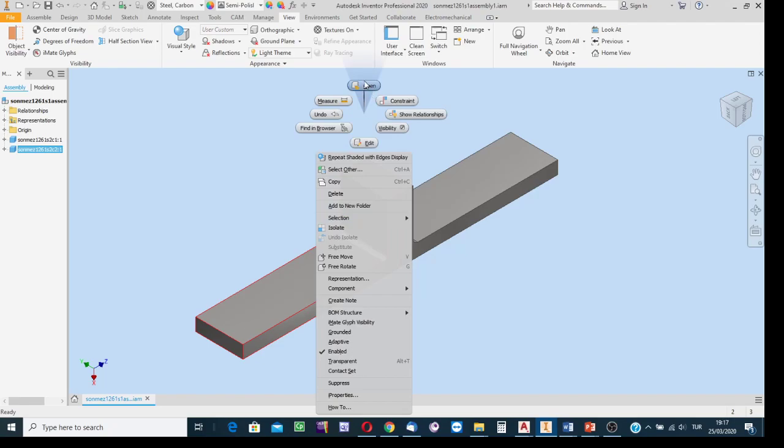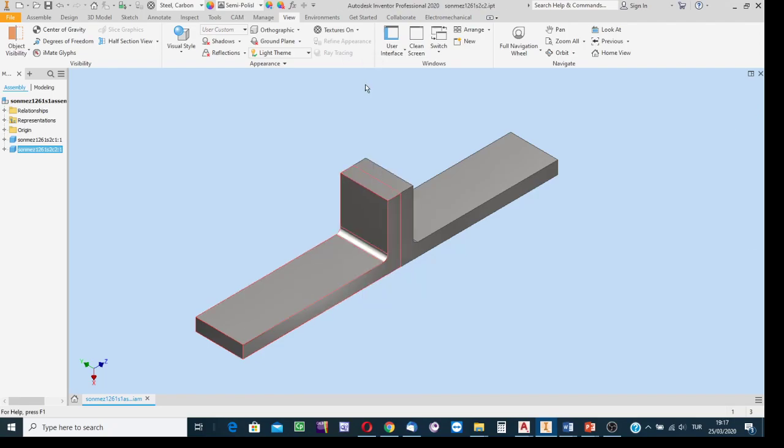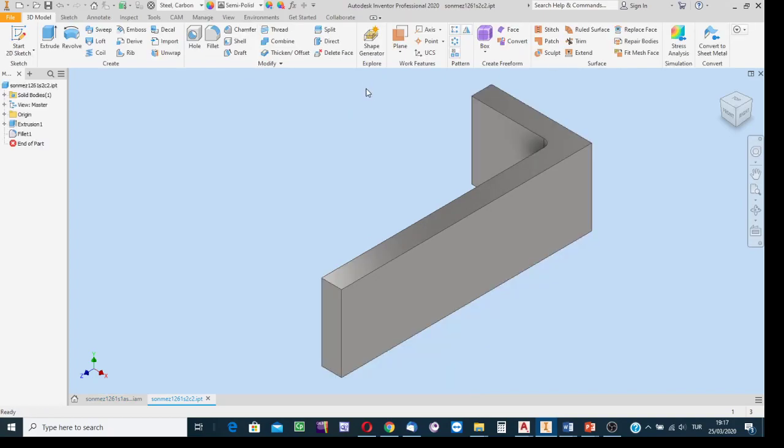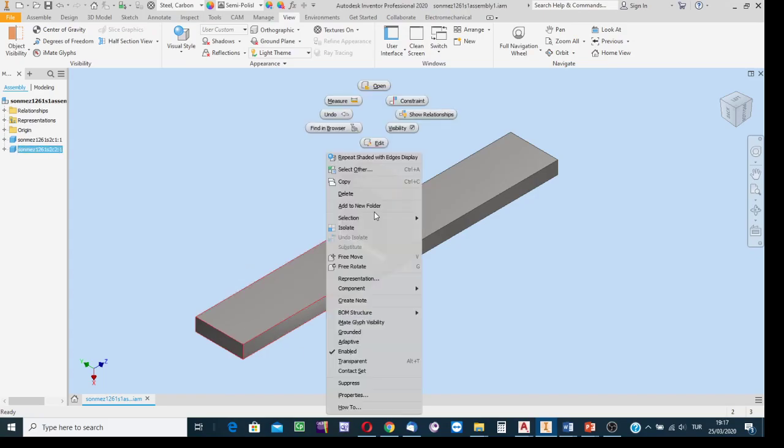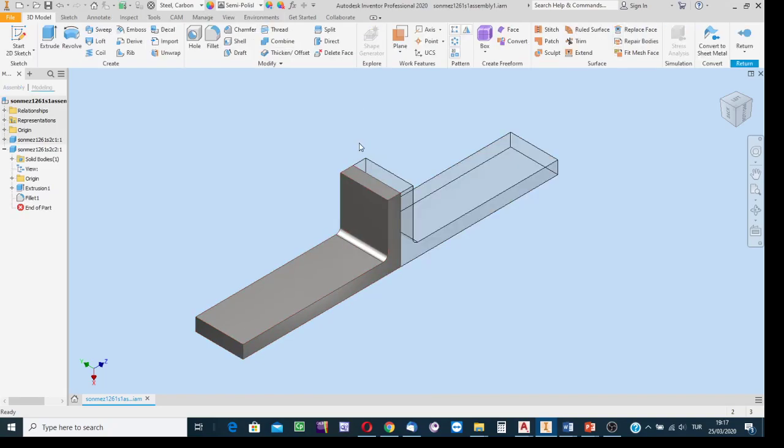If you say open after right clicking, select this option, then this means you isolated that selected component. Thereafter, you find the component in parts creation environment. Be aware. Close this file. But if you say not open after right clicking but select edit option, then without leaving assembly environment, this means you selected that one. It is as if in part creation environment.